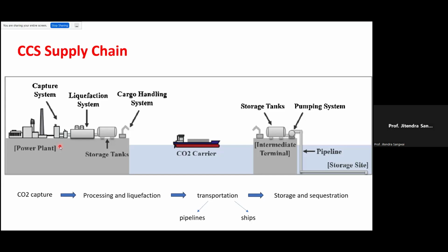So even if it looks attractive right now to convert CO2 into some of these products, you have to really understand what the process is and whether each component of that process can generate a carbon neutral balance. Therefore the immediate goal is to capture the CO2 and sequester it. You have to dump it somewhere. One option is that you can dump it onshore, and the other option is that you can take it through pipelines or transport it by ships to the offshore environment for sequestration, right?